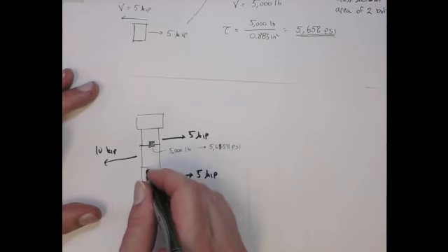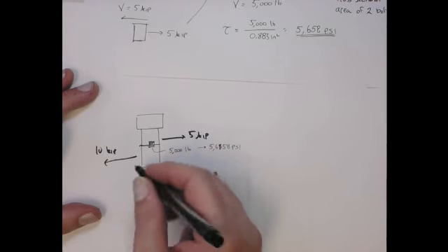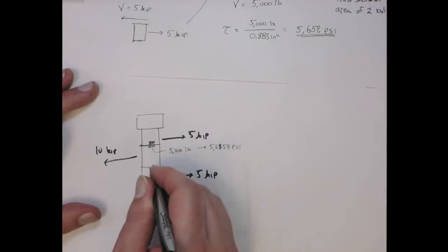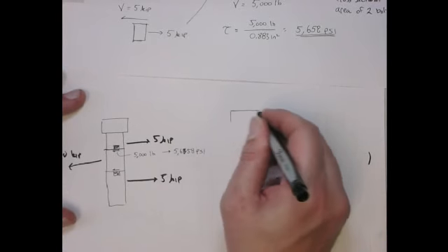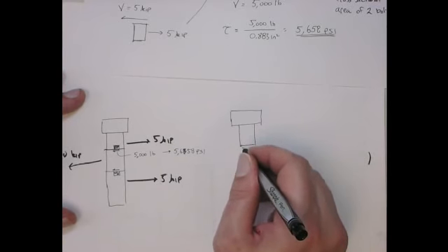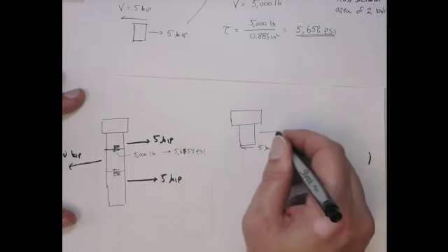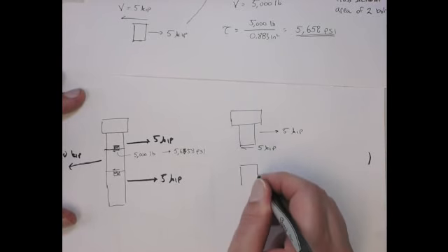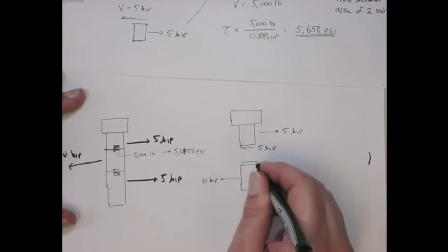Now if we looked at the other joint on the bottom, and looked at the little chunk of material here, it's another shear situation. In this case, this one will have force reacting that way. So if I kind of split these out, just to show it, 5 kip that way, 5 kip that way. And if we draw the middle section, 10 kip in the opposite direction.